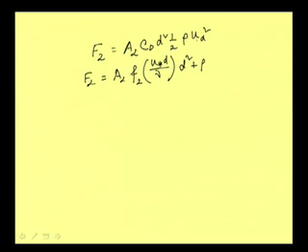Then rho, and then this u_d square we can write as u star, because u_d we know is u star into a function of u star d by nu, which we have already expressed. So when it is squared, we can write u star square and this function squared. So that way we can write rho. Okay, now rho is here and this part we can write like that. And what is the value of u star? We know that u star is equal to root over tau 0 by rho.